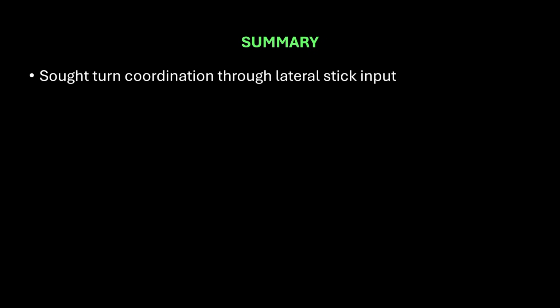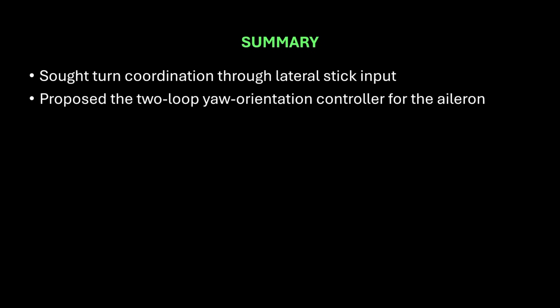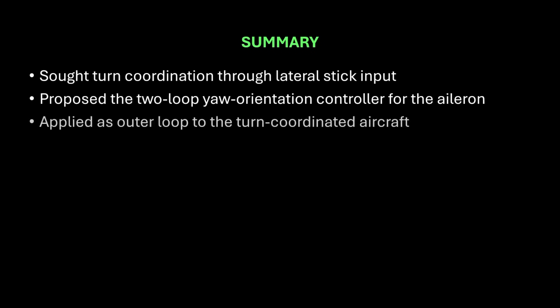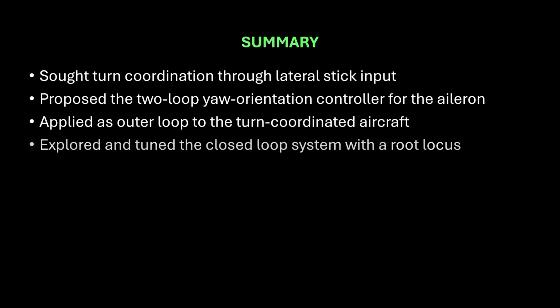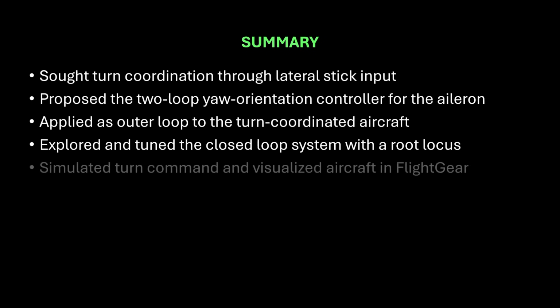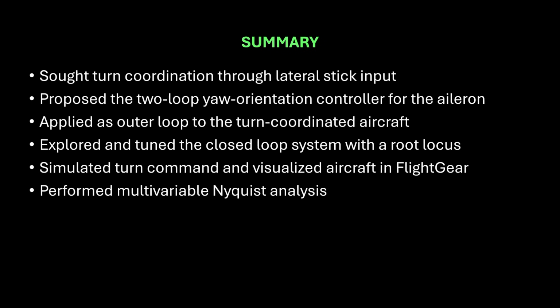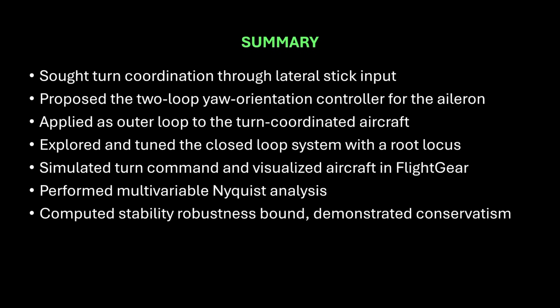We proposed the two-loop yaw-orientation controller for the aileron channel and applied this controller to the closed-loop turn-coordinated aircraft. We explored the tuning of the closed-loop system with the root locus, ultimately arriving at a tuned system and then simulating and visualizing the aircraft response to a 2 degree per second turn command. We then showed how the multivariable Nyquist stability criterion could be applied, and our results were consistent with our tuned system eigenvalues. We sought to quantify the robustness of our system with the stability robustness test, and we showed how